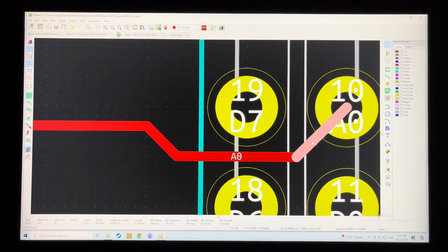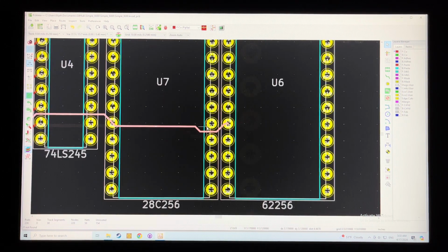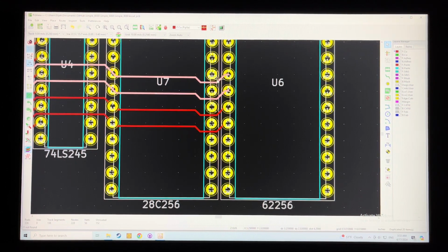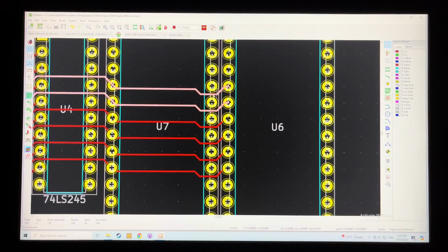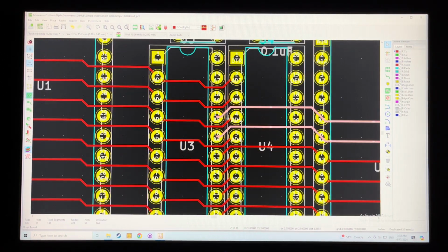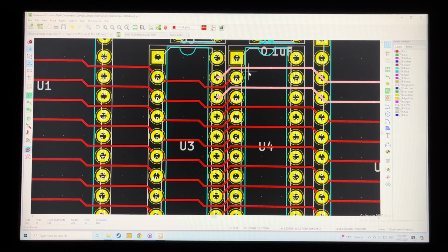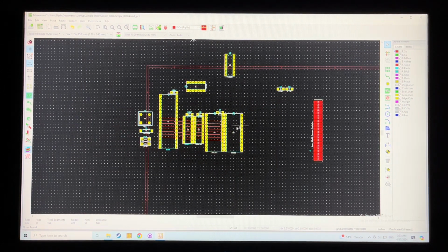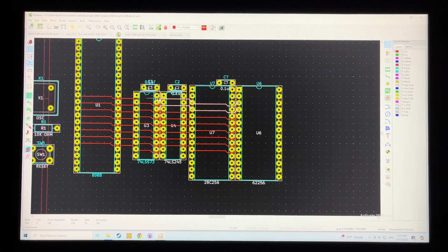I think we're going to need to drag that over and then select I, and then we just repeat again. Now when you select multiple wires, you've got to hold shift, hit I, so we're just tracing those in, and one more. Not all of them line up so neat, but it's kind of a neat way to do it. And that's how I place all my wires.